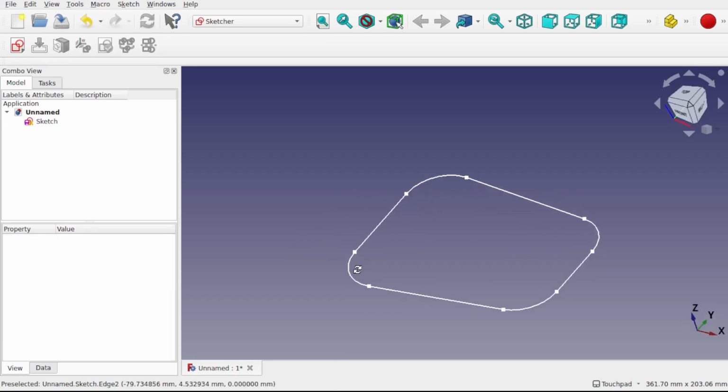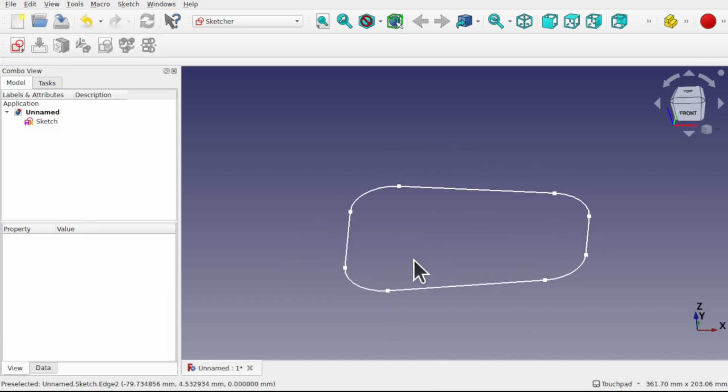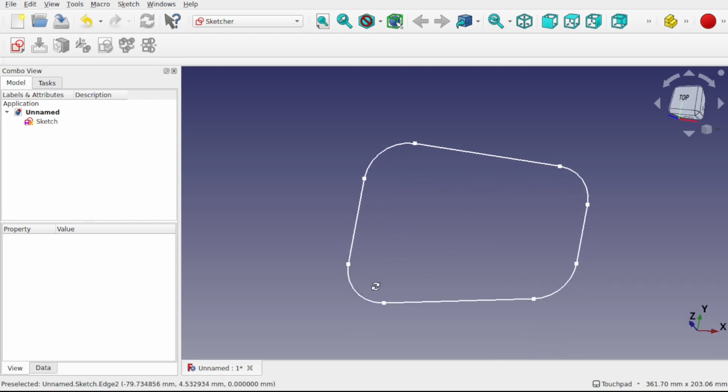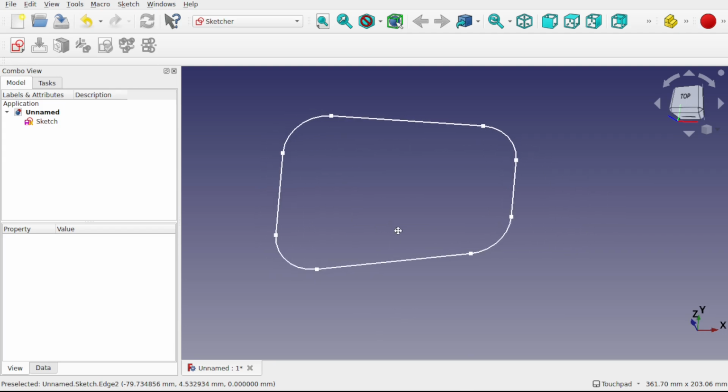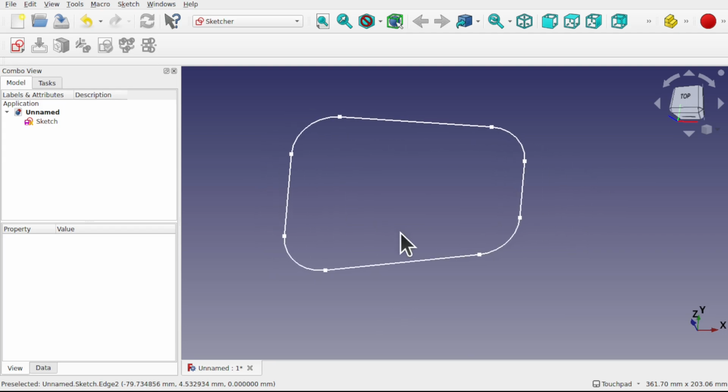Now I'm going to attach a sketch to this. If we look at our previous video where I started talking about the line OXY attachments, you'll notice that I created a sketch and then attached it. This time we're going to select the points that we want to attach to. We're going to go through this attachment style in a moment as well. So we can either look back at that video or we can get a rough idea of the attachment style here, and I'll leave a link in the description. So we're going to select some vertices to attach the sketch to.